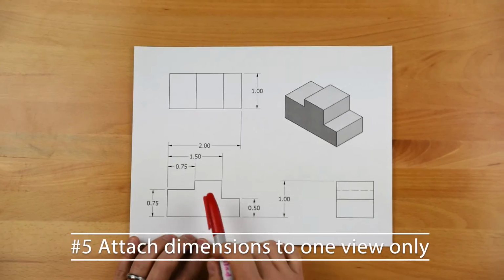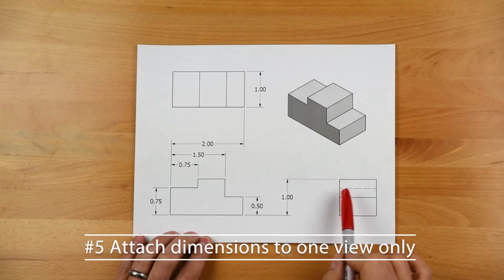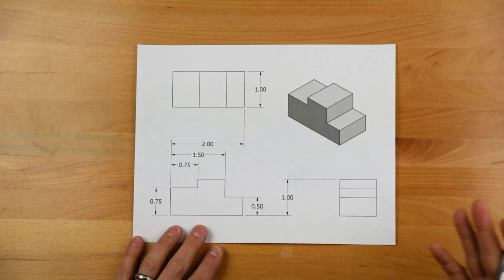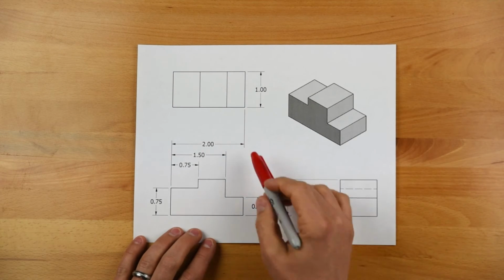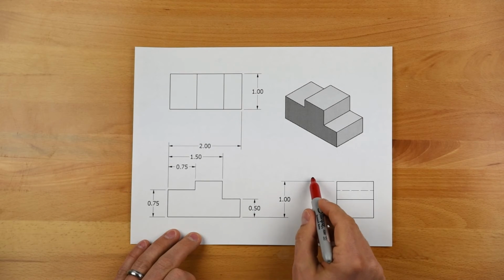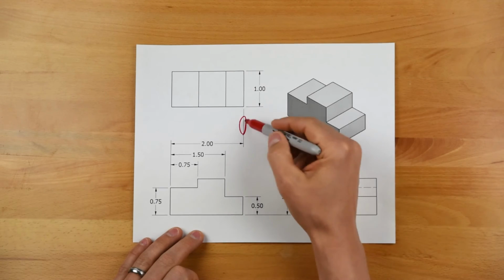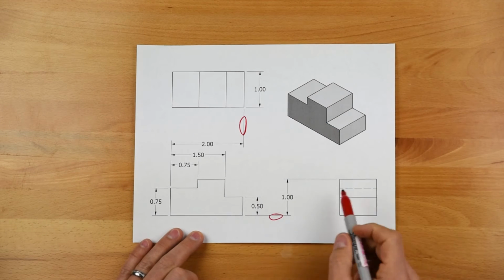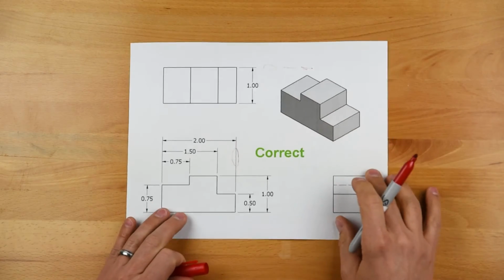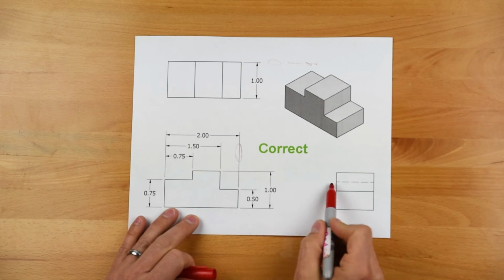Example here, you can see we're running extension lines to multiple views, and that's just a recipe for not being able to understand what's going on in the drawing. So again, we don't want to be doing this. We don't want these extension lines to be attached to different views. So again, we're going to shift that around. We're going to move everything over to our front view.